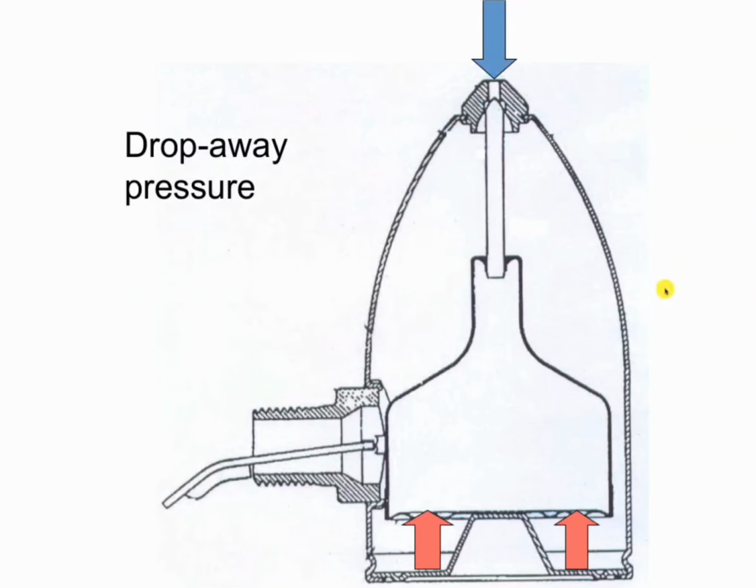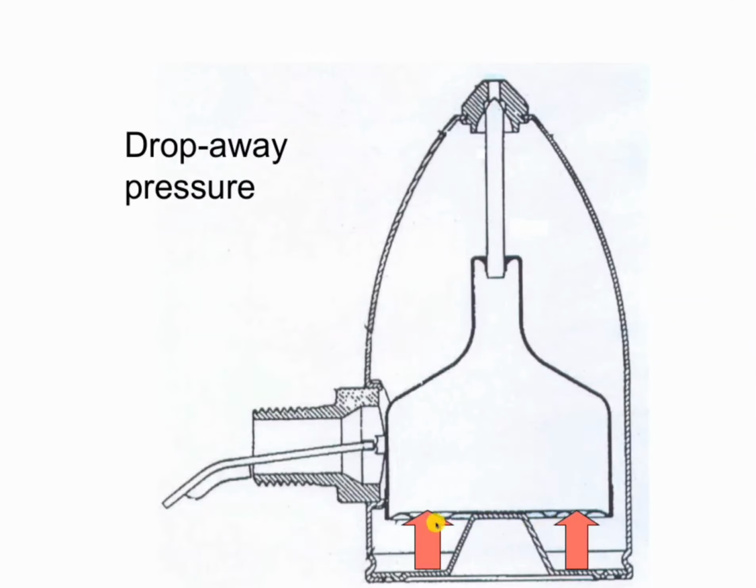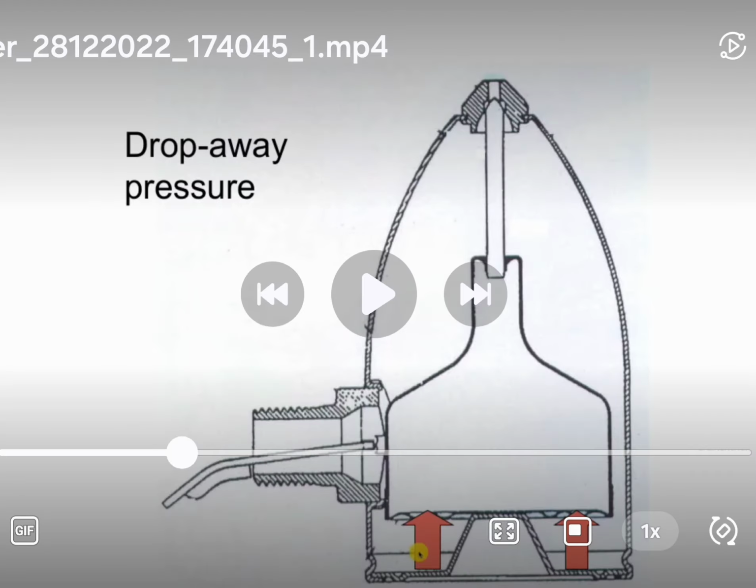I'm going to back it up some, just in case I forgot anything. "PSI or 5 PSI, whatever you're running. And you're pushing with relatively low pressure against a big wide bottom." Let's just once again take quick note of the two pressures that he referenced. And these are the cutouts he's talking about, 2 to 5 PSI. Now, I want you to go back and remember what I just told you when I showcased the picture of the electric Steam Masters boiler that I had when I was living as a superintendent, and how I ran this thing at 7 to 8 PSI. That was the cutout limit. Keep note of that. Okay.